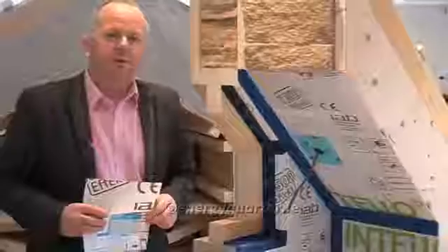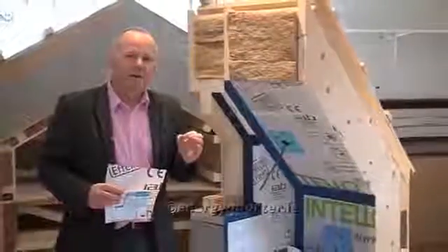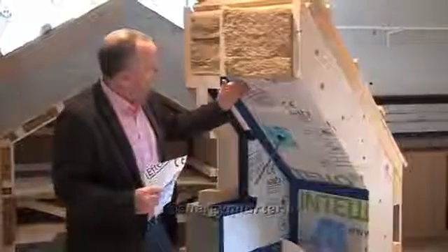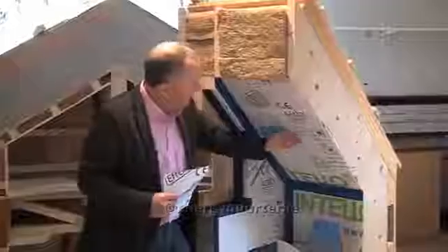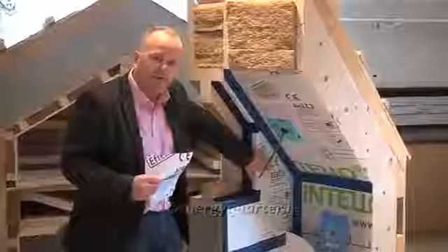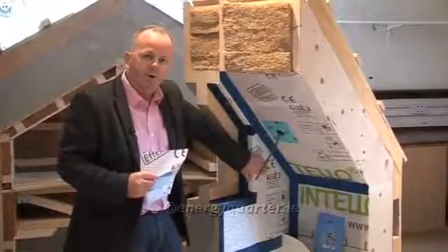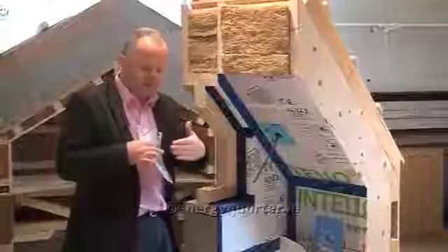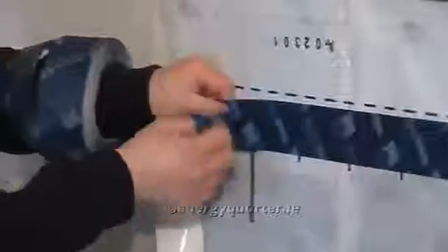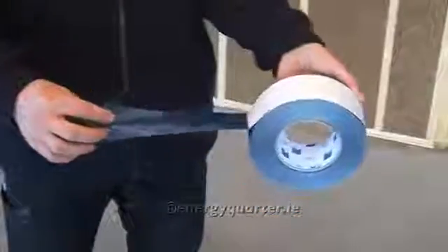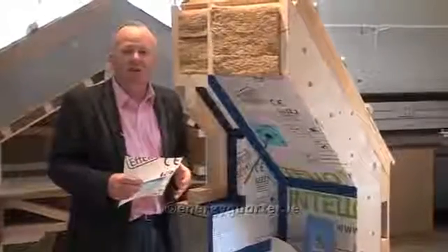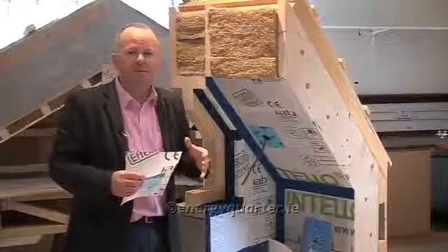So having looked at the principles of passive house airtightness, let's examine in a bit more detail how this is achieved on site. We have barriers here which are laid underneath the attic insulation. Here we have another barrier which lines the wall insulation, and it's very important that the junction between these barriers is taped, and not with ordinary duct tape or something like that, but with special airtightness tape which has been age tested, because you want to make sure that this building is going to be airtight not just for 5 years or 10 years, but in fact for decades.